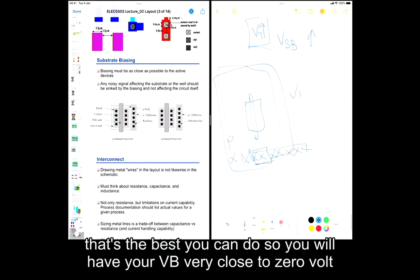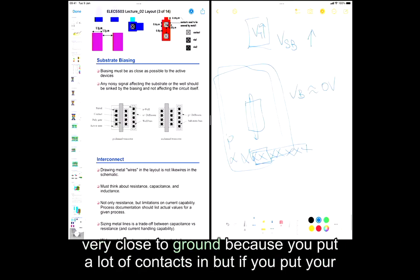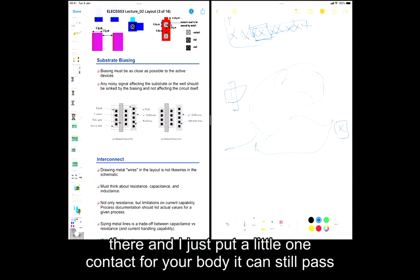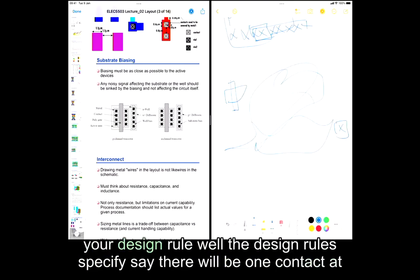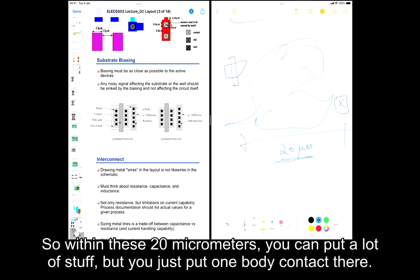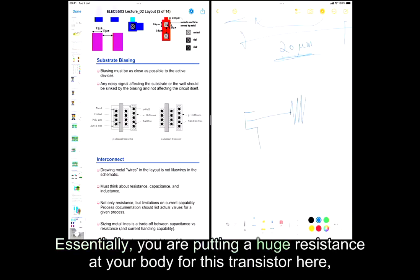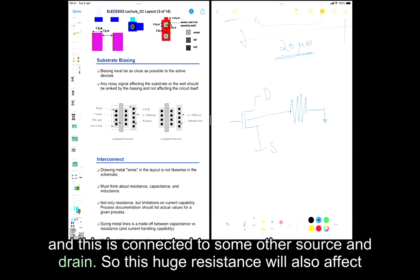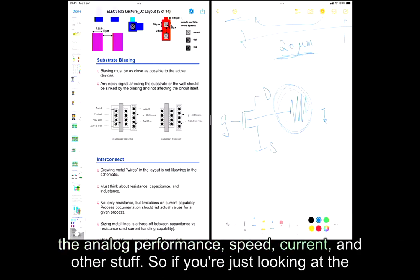So you will have your VB very close to 0 volt, very close to ground, because you put a lot of contacts in. But if you put your transistor here, and in order to save space, I put a lot of circuits here and there, and I just put a little 1 contact for your body, it can still pass your design rule. The design rule specifies, say, at least 1 contact to connect your body to ground within a range of 20 micrometers. So within these 20 micrometers, you can put a lot of stuff, but you just put 1 body contact there. Essentially, you are putting a huge resistance at your body for this transistor, and this is connected to some other source and drain. So this huge resistance will also affect the analog performance, speed, current, and other stuff.